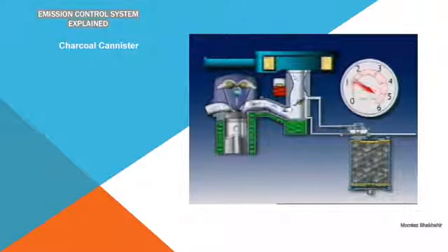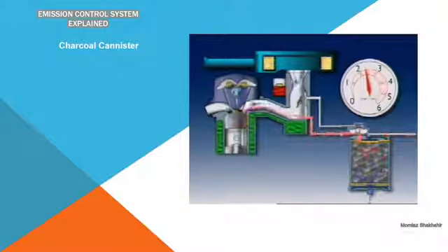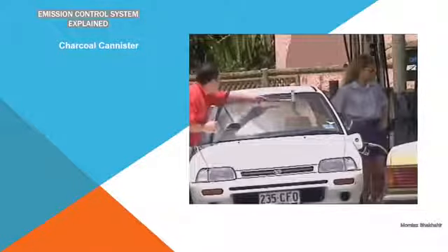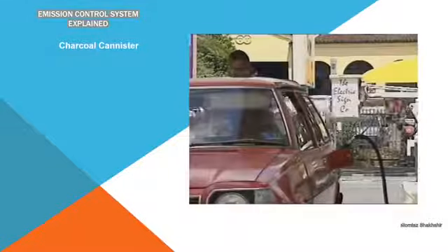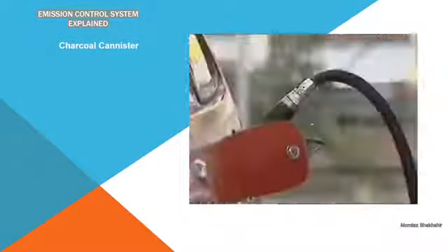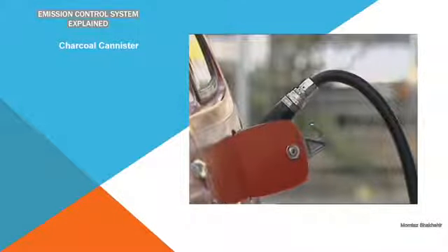The purge valve is designed to operate only at speeds well above idle. If it operated at low speeds, the extra fuel vapours could upset the air-fuel mixture, which could cause poor idling and rough running. The evaporation of automotive fuel is a major source of hydrocarbon emissions. The rates of evaporation are higher with petrol than diesel because petrol is more volatile.